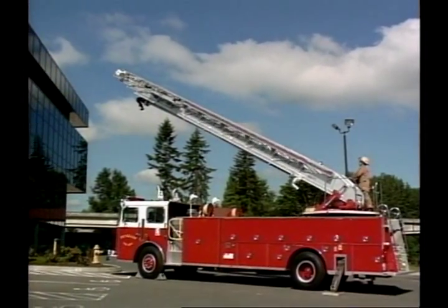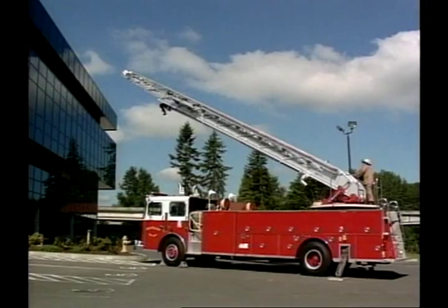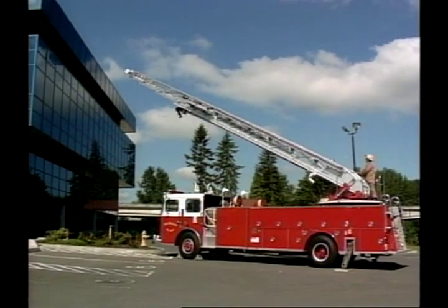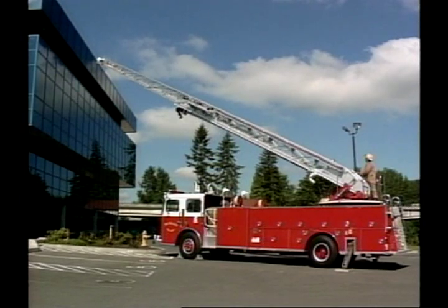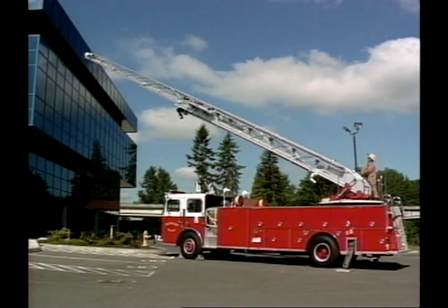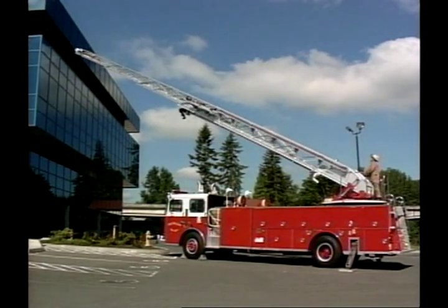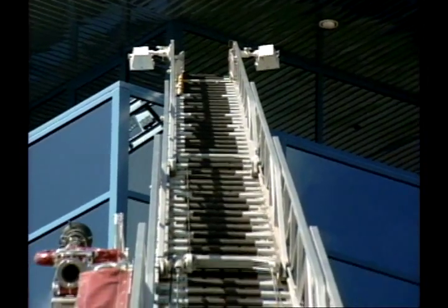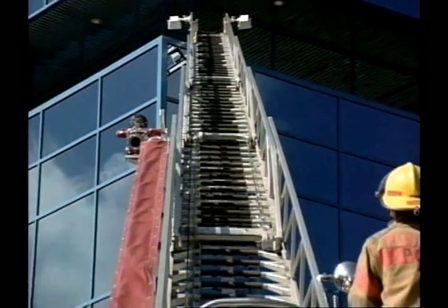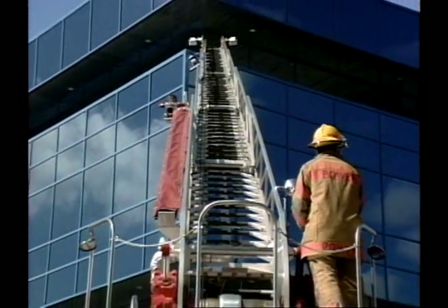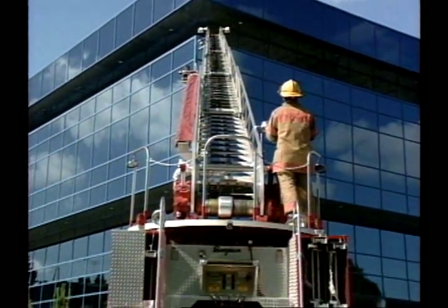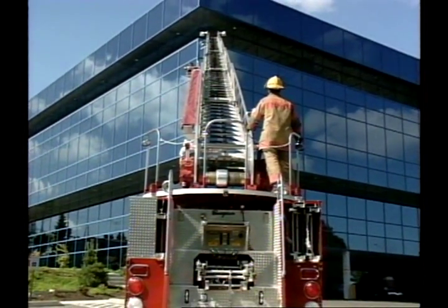When stabilizing on a longitudinal grade, position the apparatus so that it is in direct line with the intended objective of the aerial device. This means that you will operate the aerial directly over the front or the rear of the apparatus. Once again, follow the manufacturer's requirements for operating aerial apparatus on uneven terrain and stay within the loading limits for your aerial device.